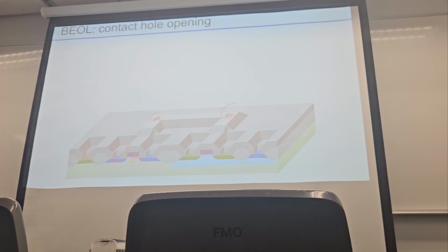The gate is here, but typically we have the connection to the outside, because if you have the metal on the top, this may affect the threshold. So that's the reason why we always have the leading line to the outside. Okay, so after filling the metal, we use the etching method to pattern the metal. So yeah, this is the gate, right? This is the source.